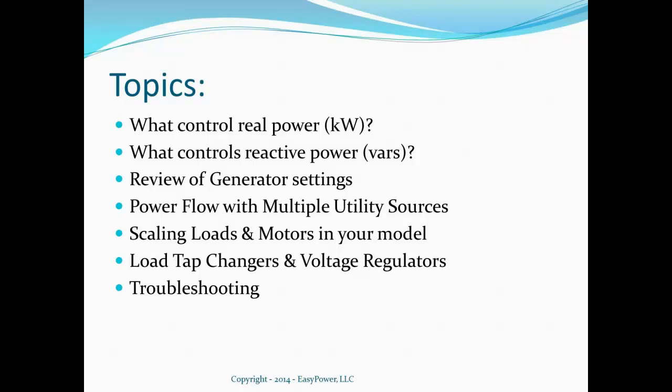And we're going to talk a little bit about load tap changers and how EasyPower has the ability to model the effect of the load tap changer, so it'll automatically select the appropriate tap to maintain whatever voltage set point you ask, within the limits of what is possible. And then if you do any work with electric utility distribution systems, you're familiar with the step type voltage regulators that are used, similar to a load tap changer, to maintain voltage within a specific range. We don't have a specific model for that in EasyPower, but we can model that as a transformer, and we'll talk about how to do that briefly.